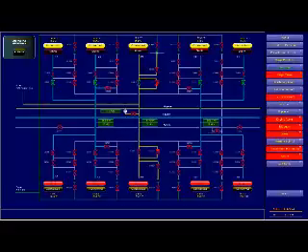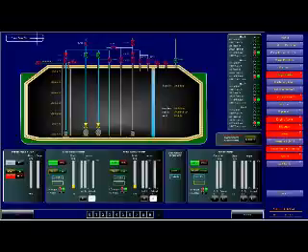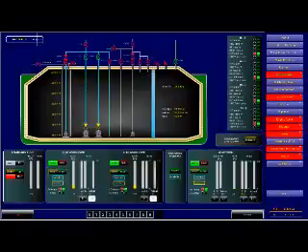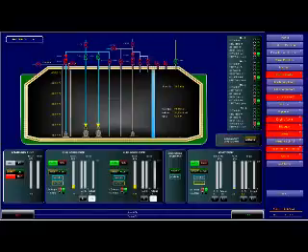And so go to the tanks. Go to number 4 tank. This is our number 4 tank, which is now very highly filled, 97%. Okay, so we want to discharge it. So we'll start, no, not this valve, because we are throwing from one pump and taking into the other pump, which is not right, isn't it? Yeah. So just close this valve. Yeah, sorry, close this valve and open this valve.